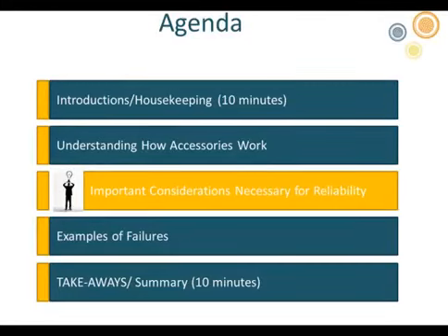So you have less dielectric losses in those materials than you do others, but typically cross-link polyethylene has lower dielectric losses than EPR, as well as a lower dielectric constant, because typically as your dielectric constant increases, so do your dielectric losses in the material, and that's why you get the dielectric heating in the high K stress control tubes or high dielectric stress control tubes, because they have more dielectric losses.